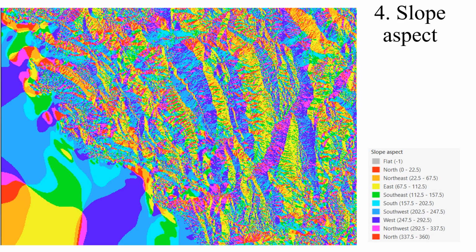The morphological aspect. This actually shows the orientation of the slopes, for example, northwards, southwards, northeastwards, etc. This is important because it indicates the effects of the weather. For example, in Greece, we know that most weather phenomena, for example storms, come from west to east. Thus, a west-facing slope will be directly exposed to them, while an east-facing one would be better protected. Thus, the former slope will have a greater problem of runoff erosion and landslides.